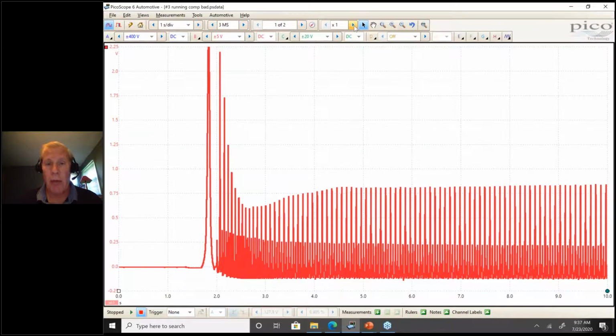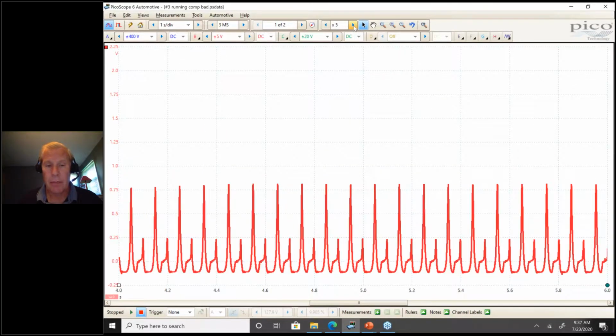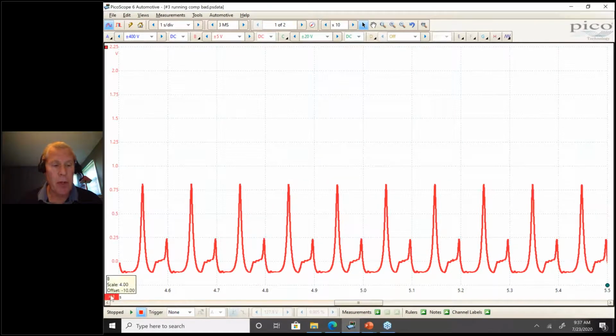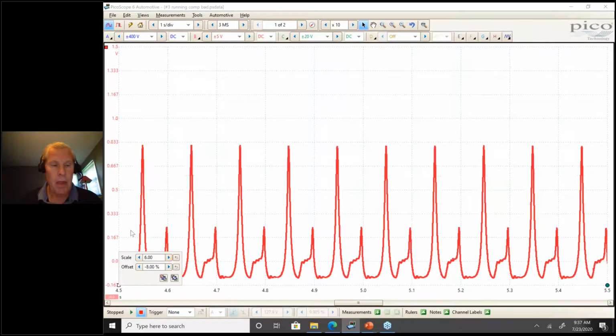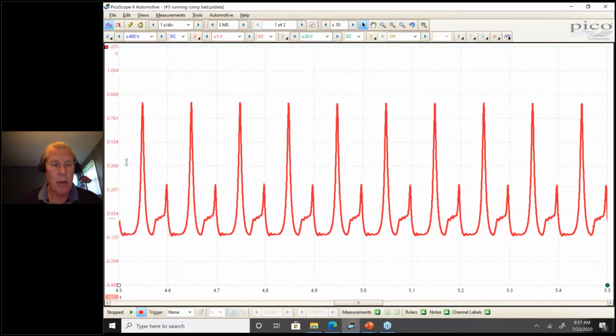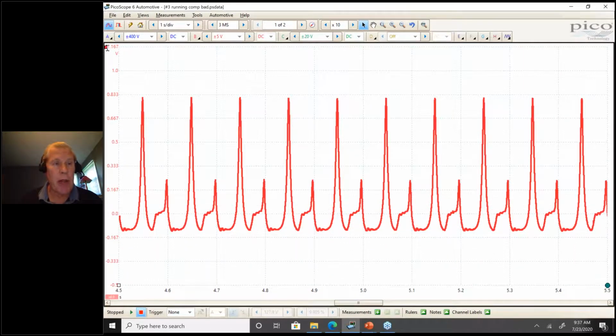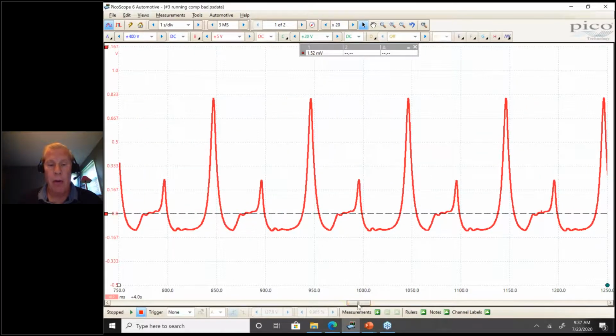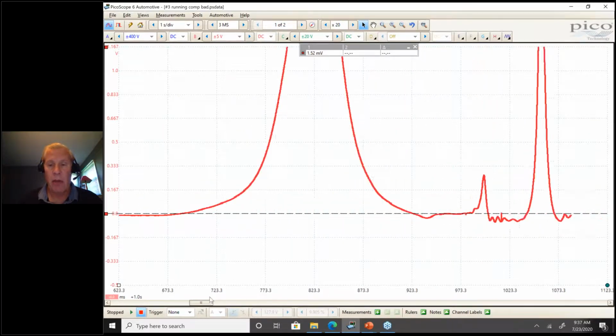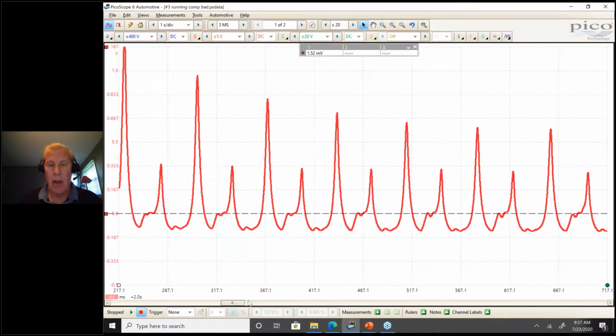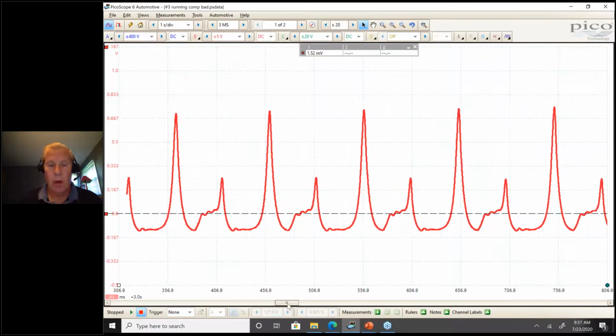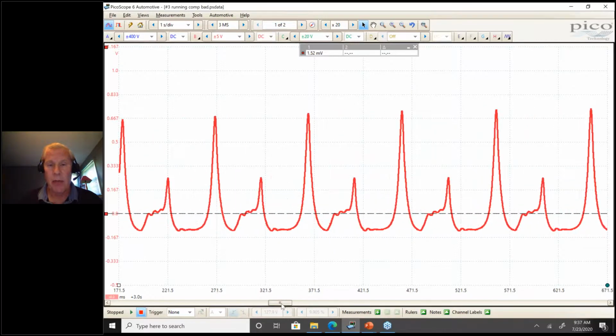So I'm going to start to zoom in horizontally first. Then I'm going to zoom in vertically. Then I'm going to lift the pattern up a little bit. And I'm going to bring my cursor down to my 0 line because we're dealing with exhaust path restrictions in this discussion. And you can see right away, there's something weird with the exhaust stroke. So I'm going to zoom in some more. If I walk through the pattern from when the engine was first cranked and started, and then the pressure stabilized, whatever's going on, it's consistent.